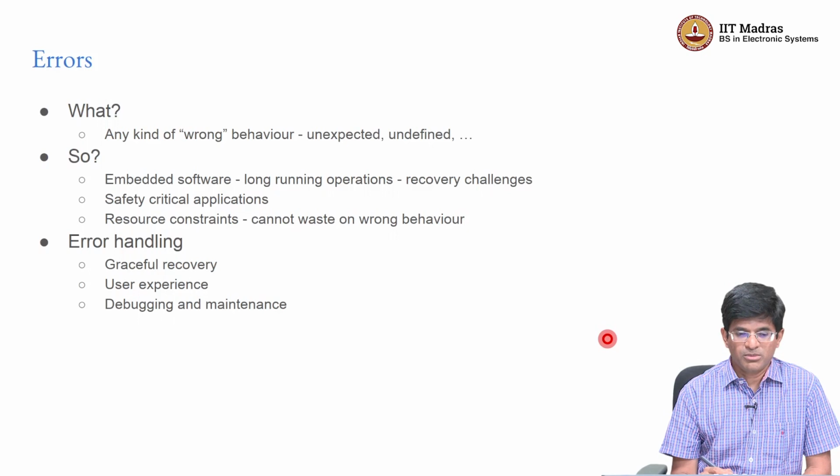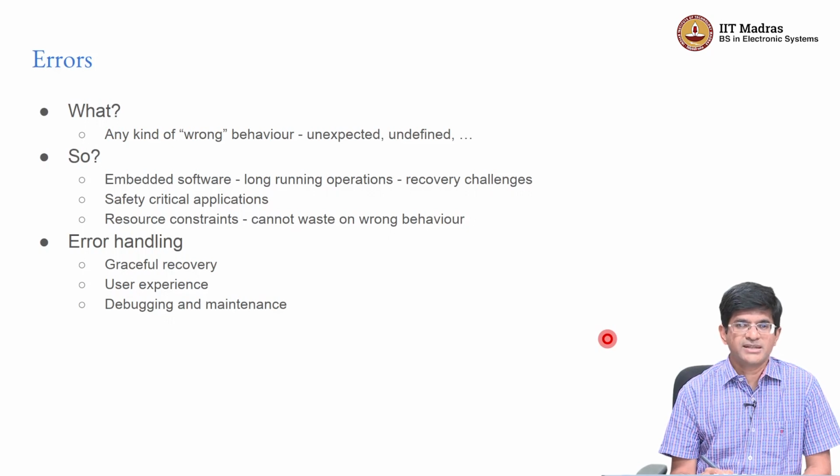So what's the problem with errors happening? Embedded software typically is long running, meaning that you have embedded systems which once you switch them on are expected to pretty much just work and work and work, and restarting or resetting the system repeatedly or often or even at all could be difficult. There can be safety critical applications including things like nuclear power plant control and so on, where essentially resetting the system is not an option. You don't have a choice, you have to have the system working correctly at all times.